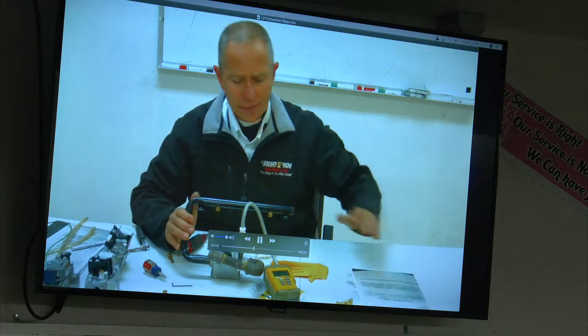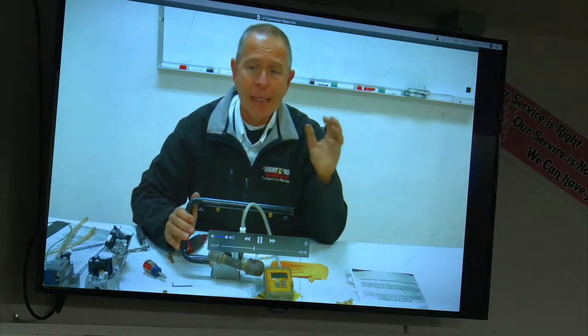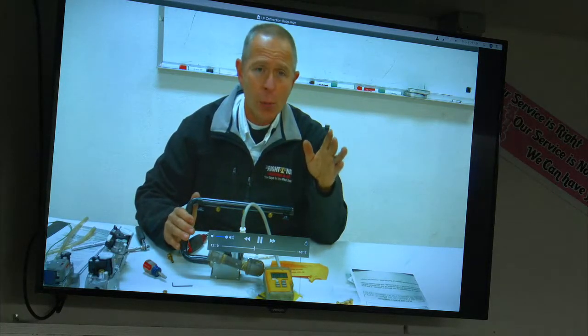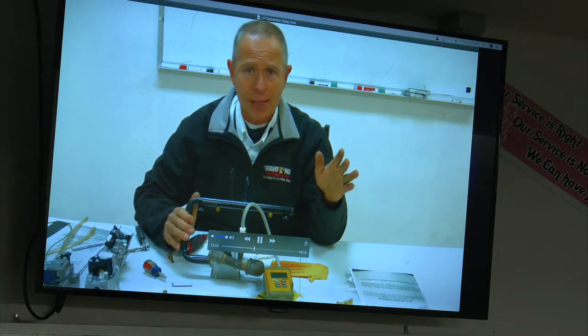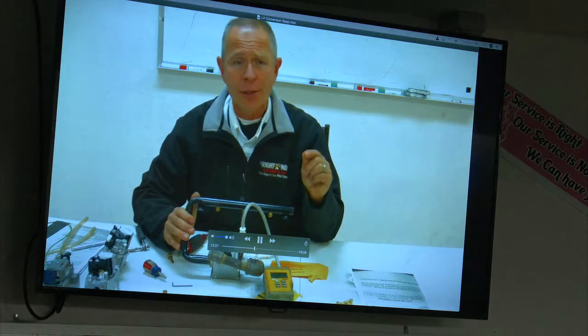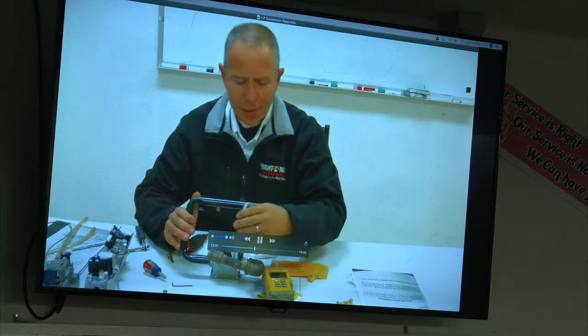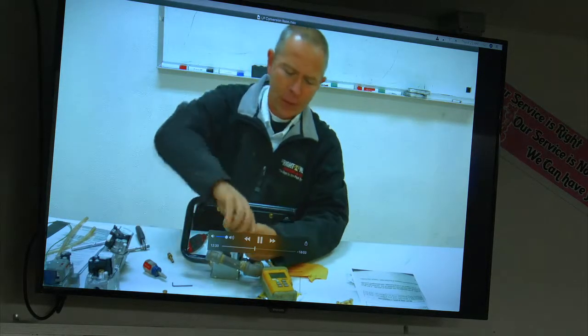So once we have confirmed by firing, we're going to turn the gas off, leaving the furnace blower running so that we do not overheat the limits and you spend the next 15 minutes to half an hour waiting for those limits to cool down before you can do your next measurement or adjustment, okay? So with the gas turned off, we are going to take this off.